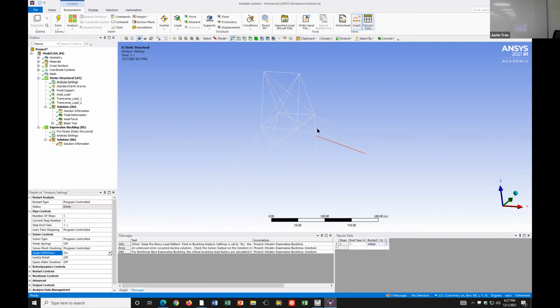The deformation shape was a big something. So remember these are just the shapes, and so these aren't true deformations. And so don't take these numbers seriously. The only thing that you should use these shapes for is just to see what they're going to look like. So actually go change instead of true scale, because these numbers are meaningless, so do the auto scale. If you do true scale, then it looks kind of crazy.